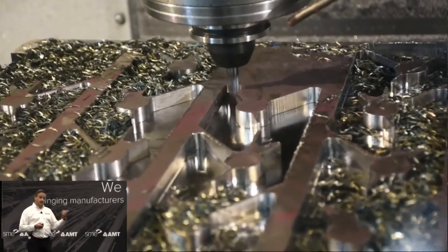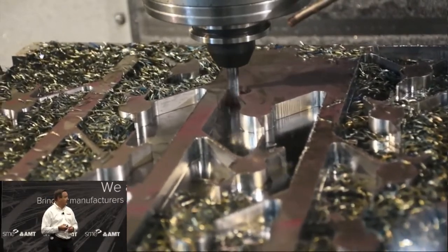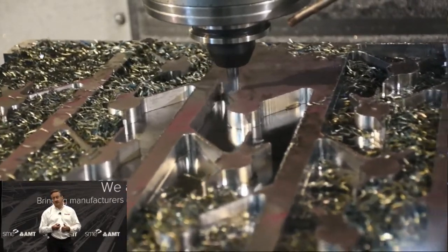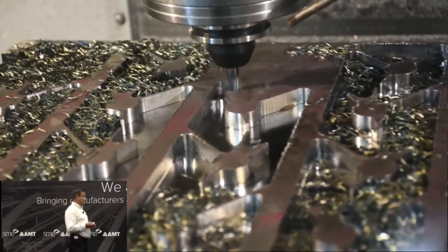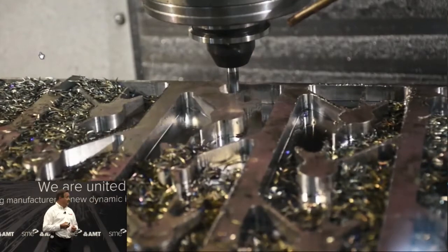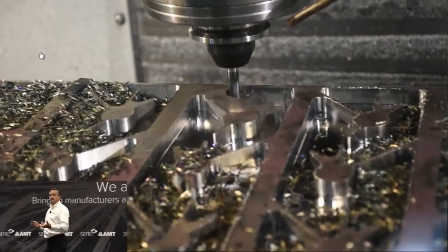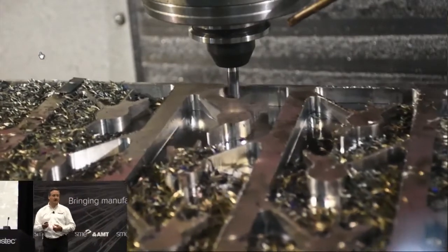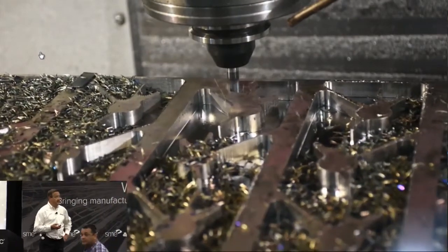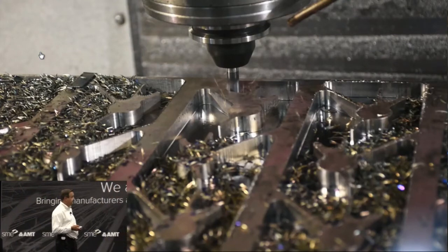So the more expensive one had a little bit more leg room, a little bit more runway to work with, and we basically ran each tool until you start seeing it glowing, to the point at which we felt we were missing out on the tool edge. We're actually compromising the tool to a point where we can no longer get useful life out of it.